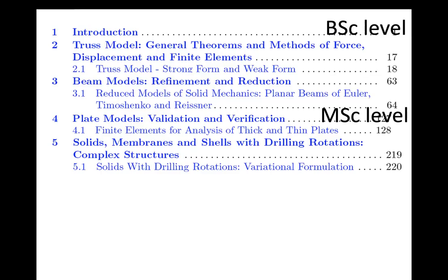And then you have a discrete Kirchhoff element, which is a very popular element for thin plates. And the element developed by the late John Argyris, which takes fifth order polynomials and the second derivatives, which are curvatures, could be used for verification. It means each of these discrete Kirchhoff elements could be checked on whether it is sufficiently small, or whether you have to refine by using the Argyris element in subsequent computation when you do these error estimates.